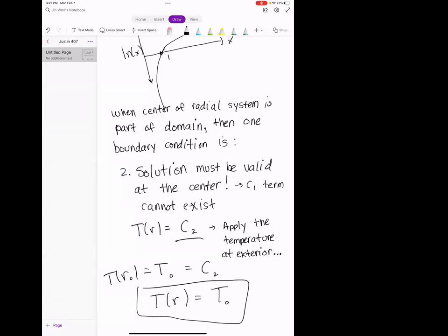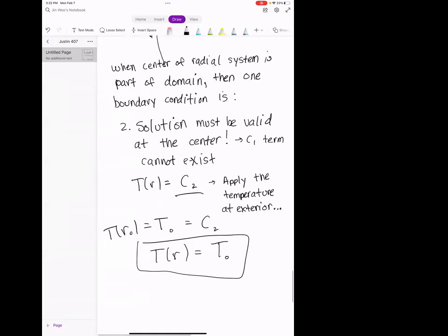And so the question is, if we were to solve this problem with numbers, would the solution just be the temperature at the outer radius? That's if it's given to you in the problem. In this case, we were given that the outer temperature was T0, and so we know that's all the way there. But I might give you a case where there's convection cooling on the outside, or maybe there's some heating coming in from the outside, like you're surrounded by a thin heater, and so you're going to have to adjust based on the boundary conditions.